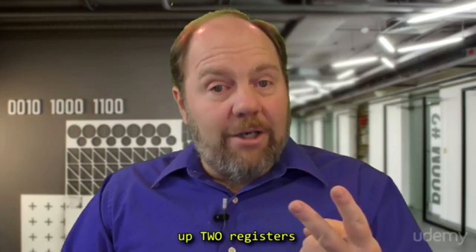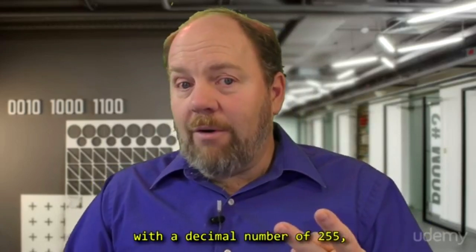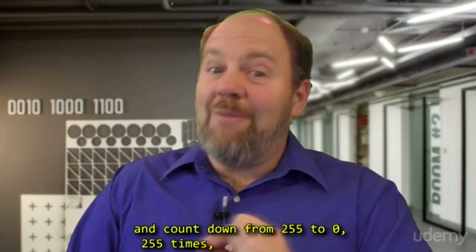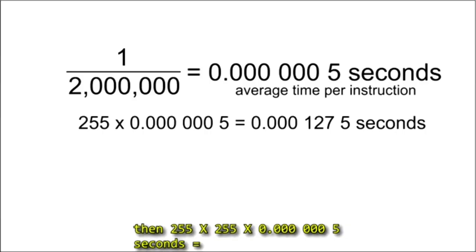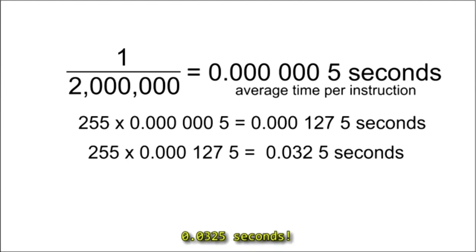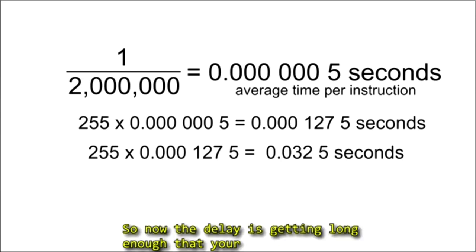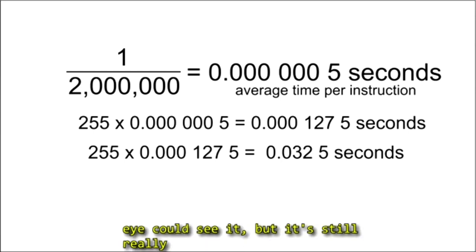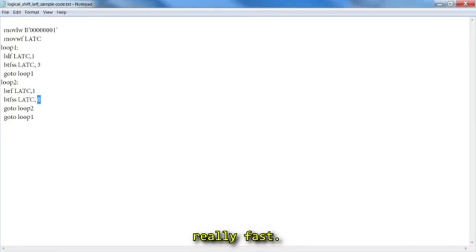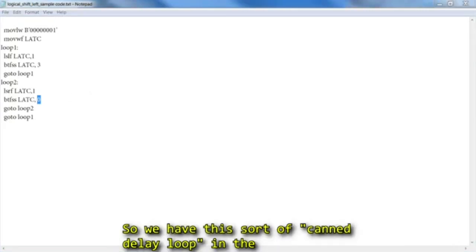If we set up 2 registers with a decimal number of 255 and count down from 255 to 0, 255 times, then 255 times 255 times 0.000005 seconds equals 0.0325 seconds. So now the delay is getting long enough that your eye could see it, but it's still really fast. So we have this sort of canned delay loop